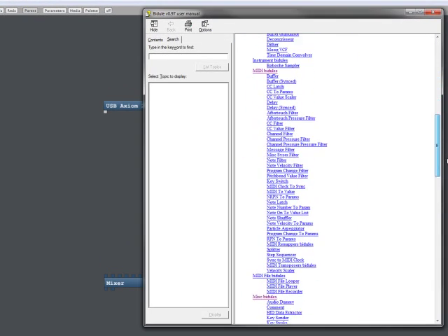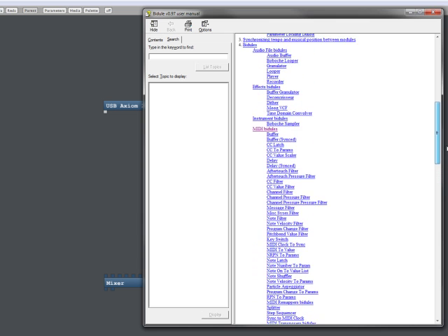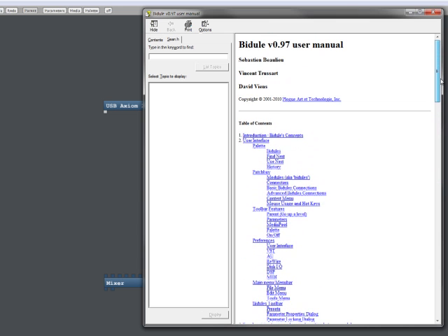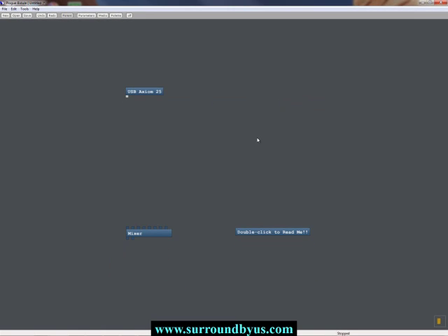There's a lot of information here, and I still find things buried in here all the time. And there's little keyboard tricks like if you hold down the control key and do up arrow, you can zoom in, or down arrow, zoom out, things like that. So there's little tricks that can save you a lot of time.